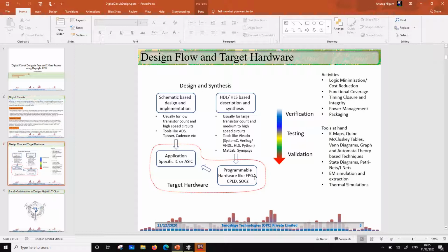In the other flow, once we have an FPGA, we can turn it into an ASIC, and there is a standard procedure to do that, right? This is mostly done by the companies who provide FPGAs, and it's a time bound, already optimized flow, so it takes less time to go from FPGA to ASIC. So people usually take the second HDL route rather than the schematic entry route.